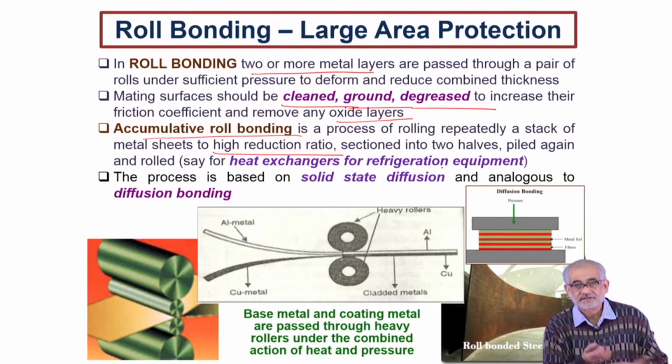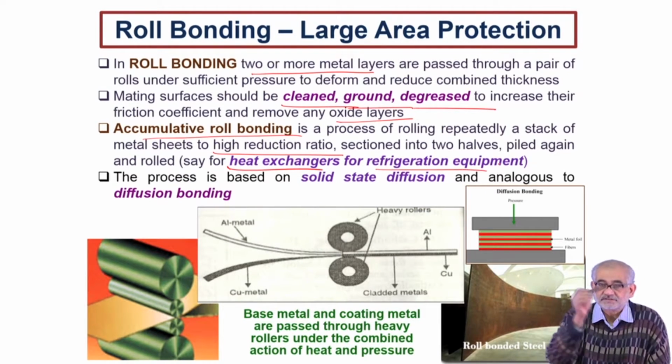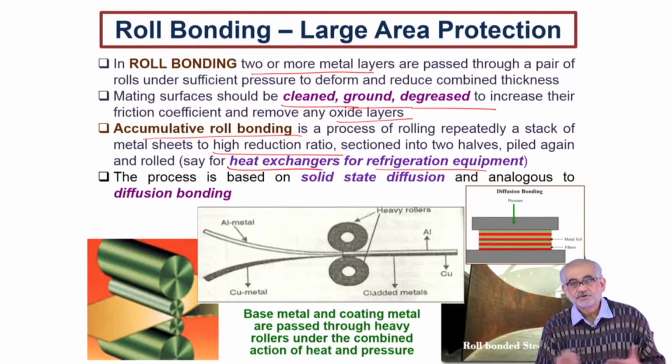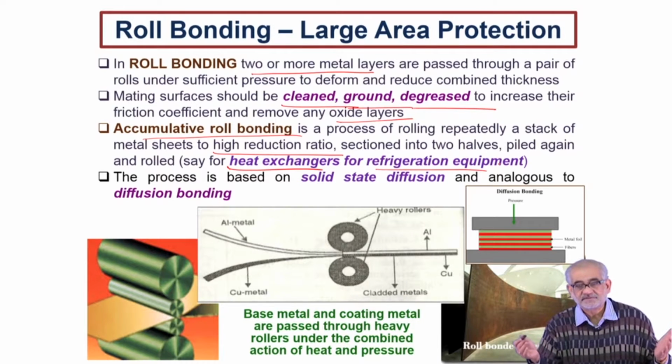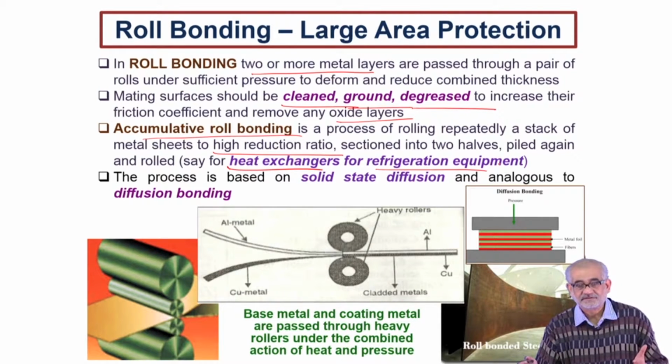What's the limitation of aluminizing, chromizing, or siliconizing process? Think of a heat exchanger or large body heat transfer medium. So you're talking about several meters by easily a meter width. To subject such a wide and long sheet to diffusional coating, you require a furnace of that nature or a bath of that nature if it's a batch process.